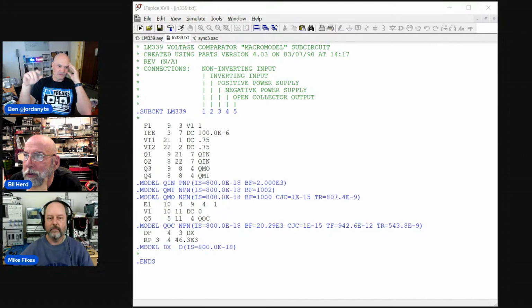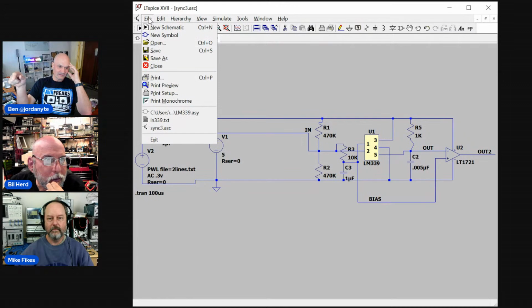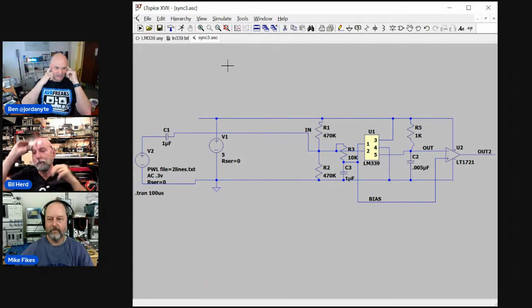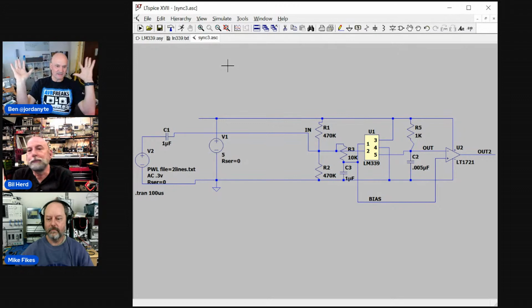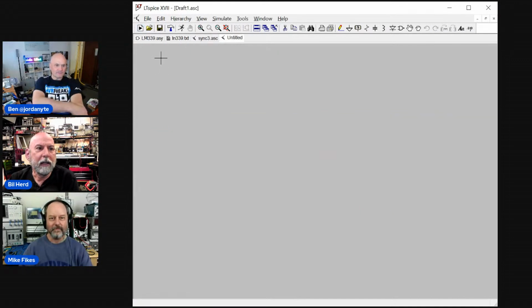I don't think LTspice was ever geared towards anything other than simulation. Correct me if I'm wrong, but you can't export a netlist for making a board from it, which some of the Spice simulation tools out there, like Microcap, can do. You can generate netlists for various PCB layout tools if you want to do all your schematic and engineering in Microcap.